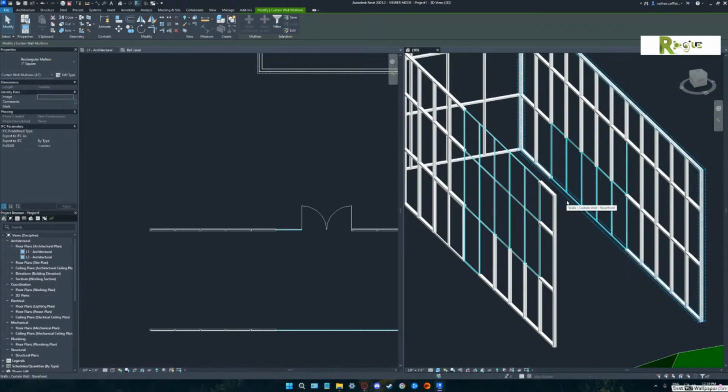And that's where people really struggle with the curtain wall that has a lot of definition and the curtain wall that has no definition. What I taught myself to do first was to take an undefined one, and I would go in and put all my grid lines in, and then I would put all my mullions, and then I was like, yeah, this is pretty good.